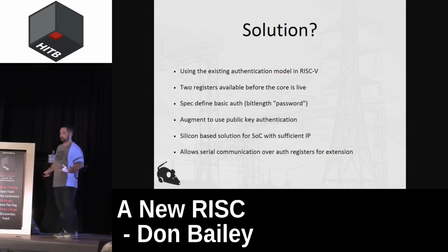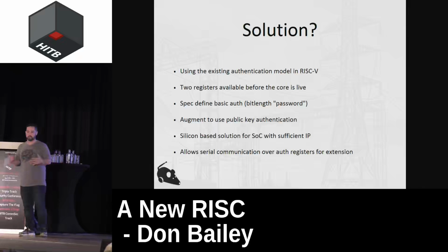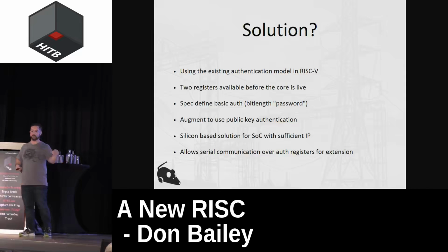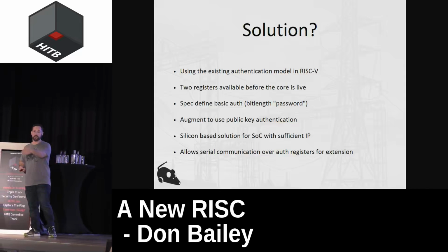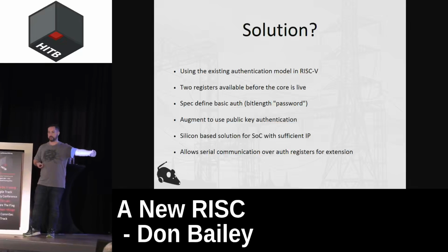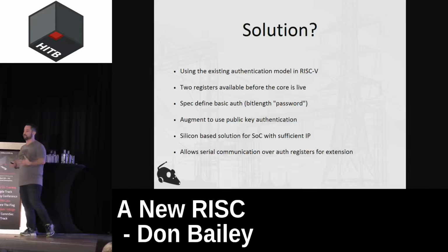What's really easy to do is we basically just have a signature checking algorithm that ensures that something has been signed by the proper key. So you basically say, all right, we're going to sign this authentication message. This authentication message is going to validate open access to JTAG, but it's also going to be signed by this root key for this manufacturer. So you get the ability to have this dual signing that can be validated in silicon or mask ROM that no longer has to be